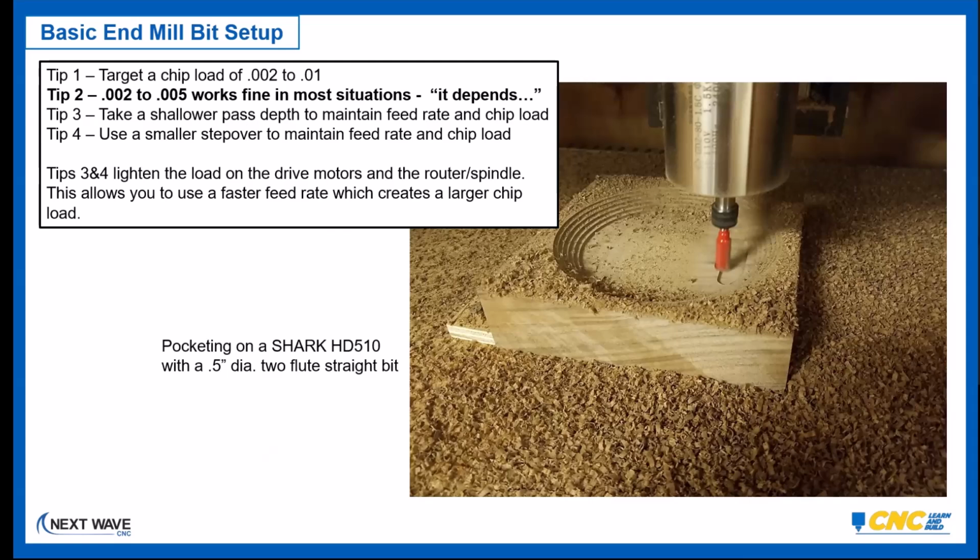Even though I said a single flute is better for chip load, even with this 2-flute, I was able to get an excellent chip load. And you know that when you're getting shavings off the project. Now, you won't always get shavings that are this nice, but in some projects cutting solid wood, you should be able to get some nice shavings with many of your bits like this. The shavings may be tinier, but if all you're getting is truly sawdust, then you probably need to go back and reset some of your tool settings to increase your chip load.